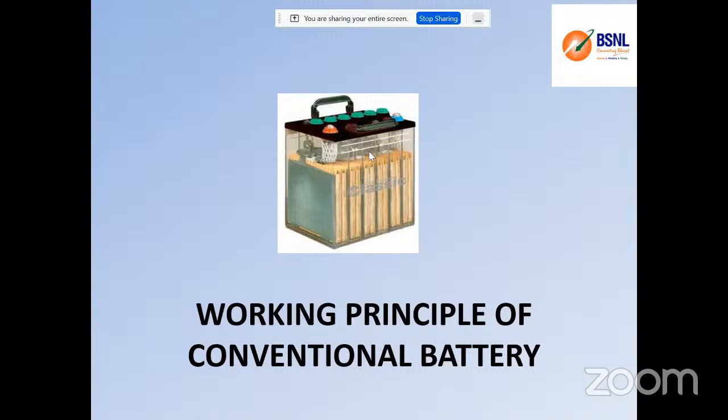So are you getting the differences? If the loads are critical, and do not allow even a fraction of a second of power failure, they always expect an uninterrupted power supply. So our choice should be UPS. That means the uninterrupted power supply providing service is called UPS. If the loads are non-critical, like a TV, a refrigerator, an air conditioner, tube lights or fans, like the majority of home appliances, we can go for inverter mode, where small interruptions are allowed.